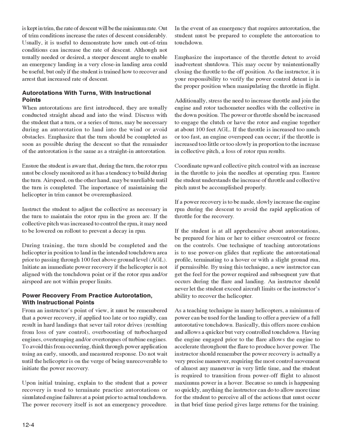Power recovery from practice autorotation. With instructional points from an instructor's point of view, it must be remembered that a power recovery, if applied too late or too rapidly, can result in hard landings that sever tail rotor drives, resulting from loss of yaw control, overboosting of turbocharged engines, overtemping and/or overtorques of turbine engines.